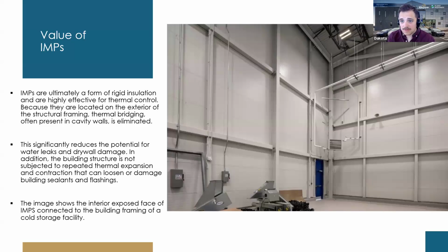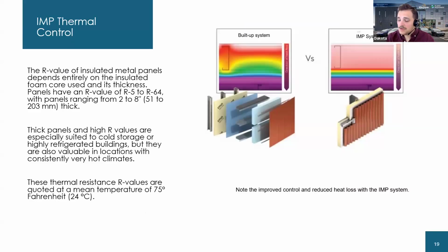It can be exposed, and due to the redundant nature of that steel, insulation, steel, we can riddle that exterior face with holes and never have to worry about compromising the weather tightness because that steel is in the background. It's kind of a double barrier system. Pretty neat.